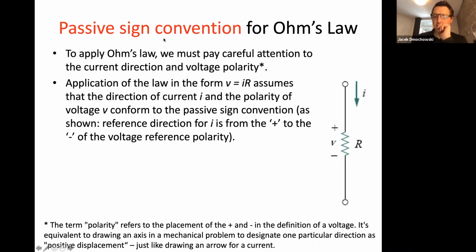So current passively does not leave the positive end. That is true as long as I is positive. If I becomes negative, for example if you solve Ohm's law and you find out I is negative, what that actually means is that the positive charge is going up in this picture, right? We'll get to a bunch of examples of that. So if that's not 100% clear in your mind at this point, don't fret, because I believe that it will crystallize once it comes down to actually solving circuits and applying Ohm's law.